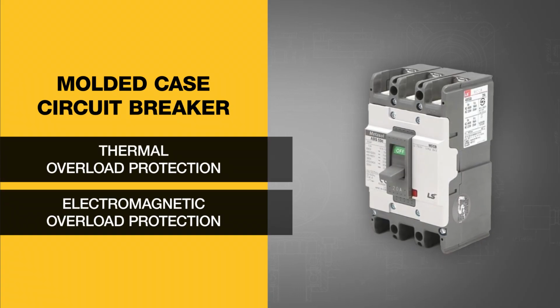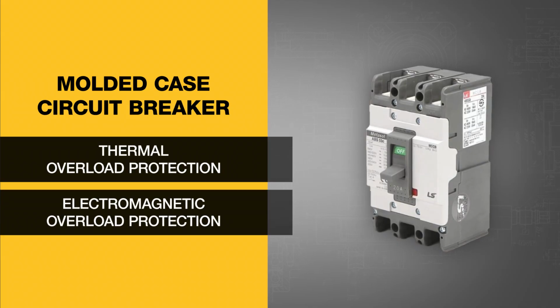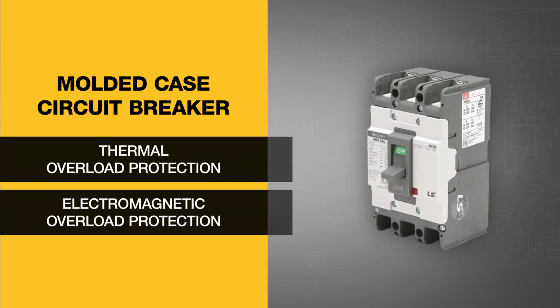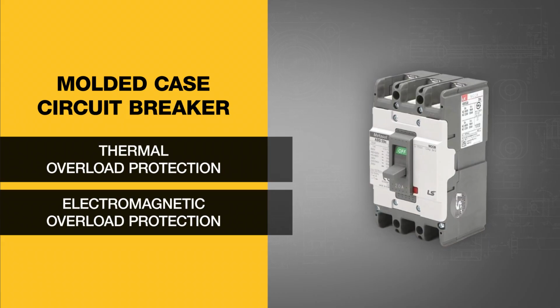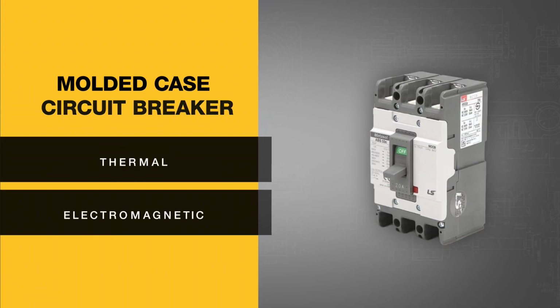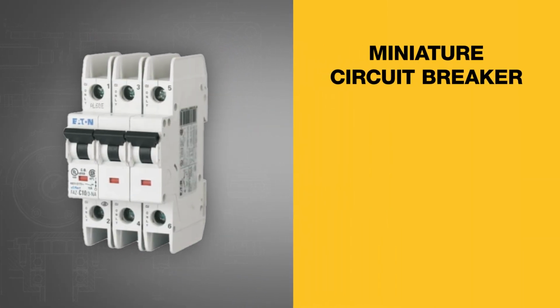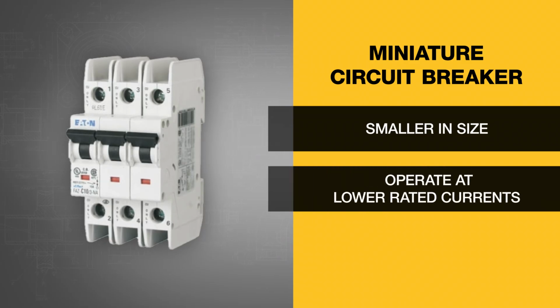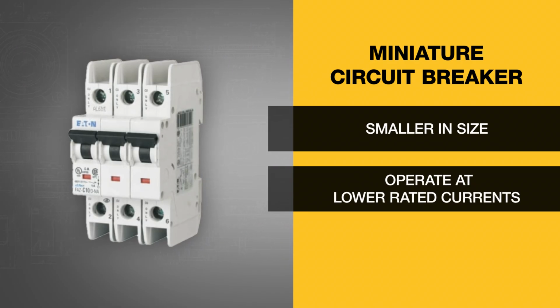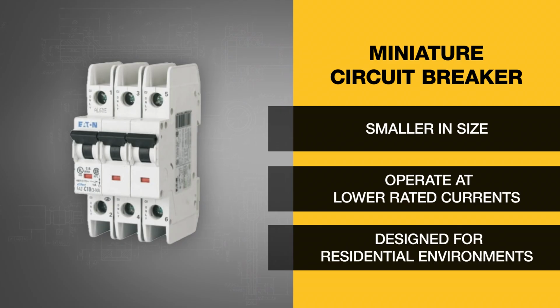The second type, electromagnetic, works off of a similar principle, but instead the inrush current generates a magnetic field, which actuates a mechanism that disconnects the contacts themselves. The second type of circuit breaker that's worth mentioning are the miniature circuit breakers. They are, as the name suggests, physically smaller than their molded case counterparts, and they usually operate at lower rated currents. It may seem counterintuitive to have a quote-unquote weaker circuit breaker, but these are designed for residential or domestic environments where having a lower trip current may be more desirable.